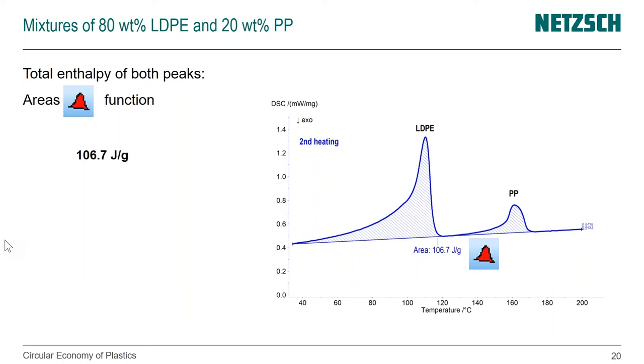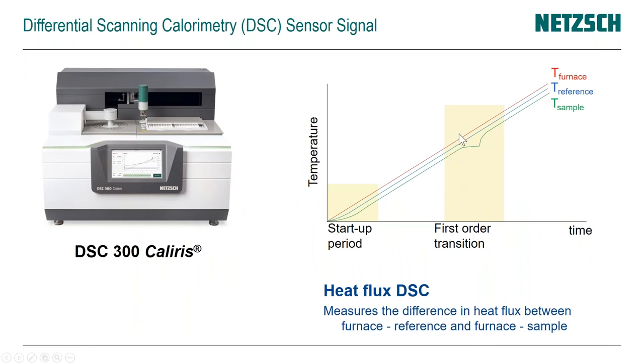Then you mentioned that knowing your reference is important. If I always use an empty crucible, how does it impact my measurement result? I'm not 100% sure if I understand and can answer that properly. The empty crucible is a reference in the sense of it allows us to really see the effects happening in our sample. You see the deviation between the sample and the reference, and you see if something exothermic or endothermic happened, and how much energy is needed.